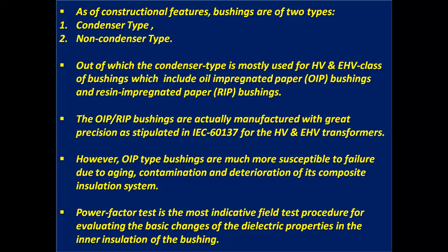However, OIP type bushings are much more susceptible to failure due to aging, contamination, and deterioration of their composite insulation system. Power factor test is the most indicative field test procedure for evaluating the basic changes of the dielectric properties in the inner insulation of the bushing.